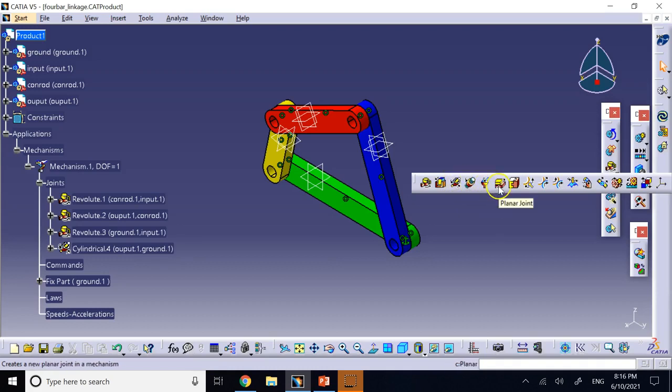You have a spherical joint, you have planar joint, you have rigid joint, all of those I mentioned for you. You have a point moving on a curve joint, you have sliding on a curve, you have rolling on a curve, you have point to surface contact, universal joint, constant velocity or CV joint, you have gear joint, you have rack and pinion joint, and cable joint, okay? And so there are all sorts of these that you can create.